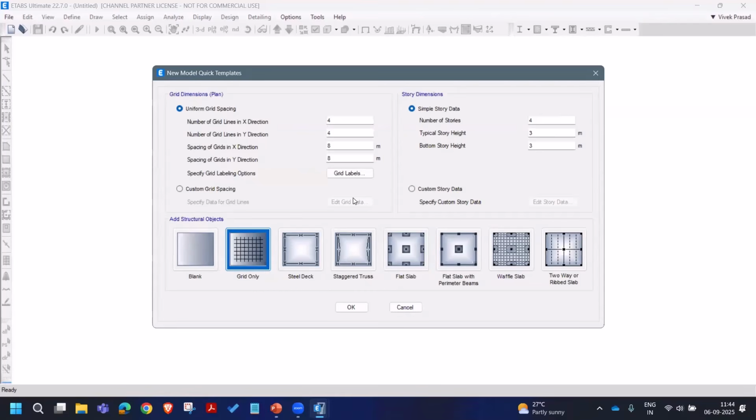Right. So the grid system. How we are going to define this grid system is, it's a single story shed type. Even if it has a mezzanine, you can still consider it as a single story and then model the members accordingly. So at the mezzanine level, you can create another level within the story and create the objects there. The program helps you on that through the grid system definition through reference planes.